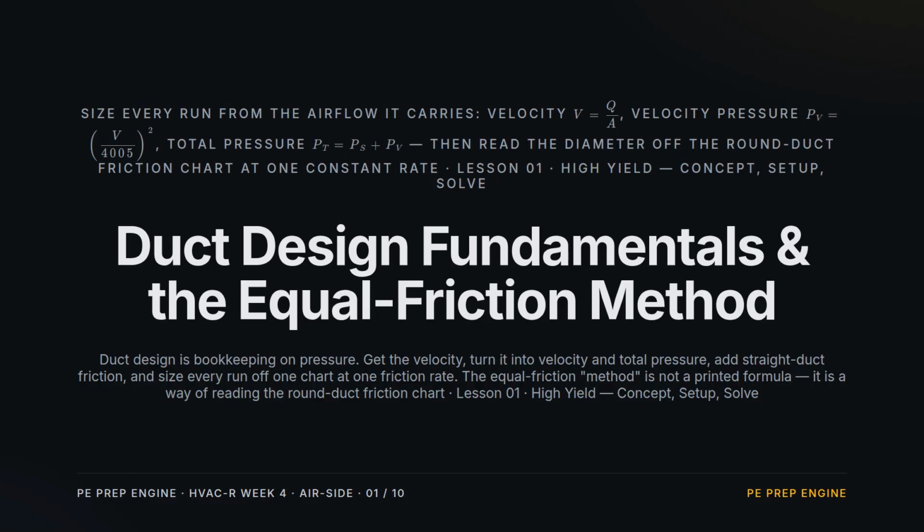Heads up on one thing the handbook does not print. Equal friction is not a named method or a formula. It is simply how you read the round duct friction chart. We'll set up the pressures, work one duct example, then hit the traps.